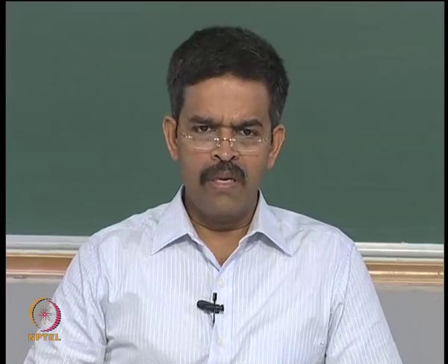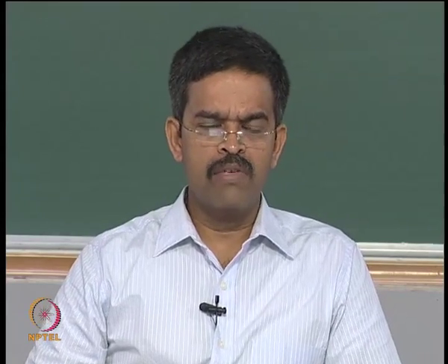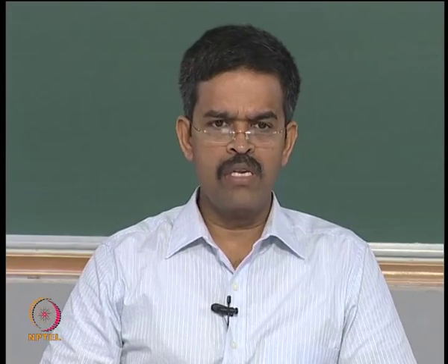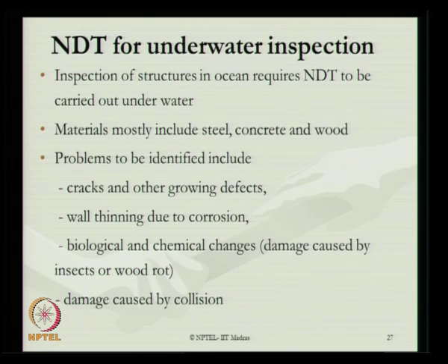NDT, ladies and gentlemen, is also a very important technique which can be used for underwater inspection. Inspection of offshore structures in the ocean requires NDT to be carried out underwater. Materials mostly include steel, concrete and wood as far as ocean structures are concerned.